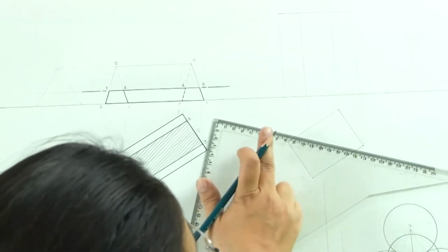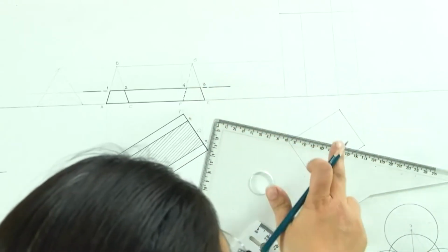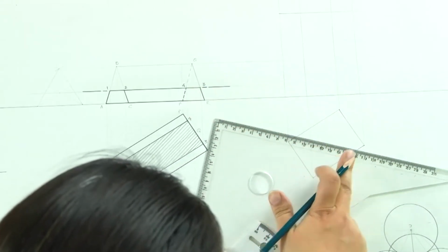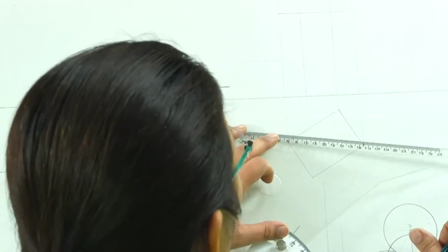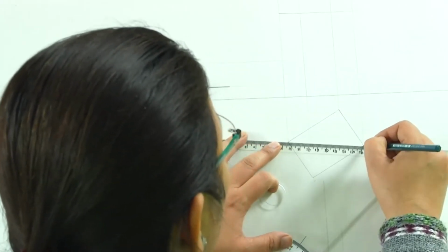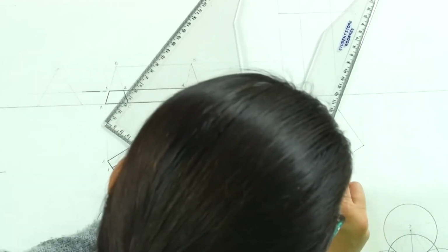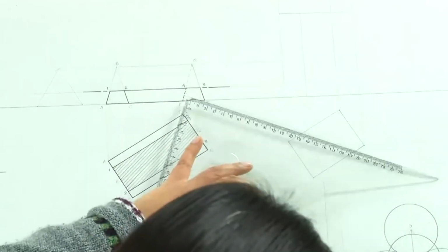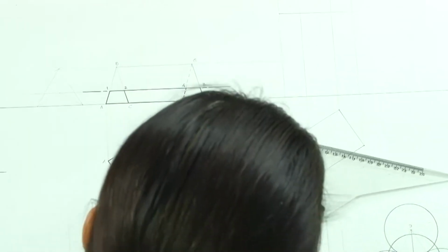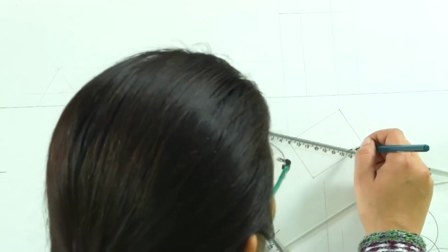So, when it is perpendicular to HP, what do we see? That one of the lines of the plane is actually going to be parallel to HP, which is what we will see in the true shape here. Now, assuming that this plane passes through the center of the rectangular prism and it is inclined at 15 degrees to VP, this is how the section plane is going to be. So, this is our section plane here.